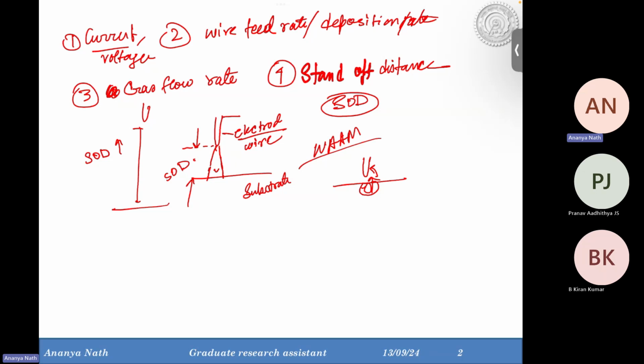Even if the circuit is completed, the height may be so high that multiple droplets come in one go, and when the droplet drops from a very top portion into the melt pool, it will spatter a lot of melted metal here and there outside the deposition zone. It will create chaos in the deposition process and make the melt pool unstable.